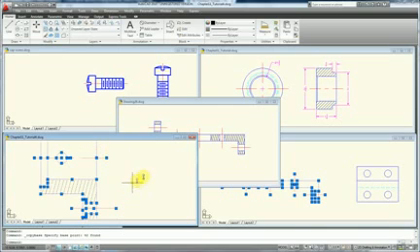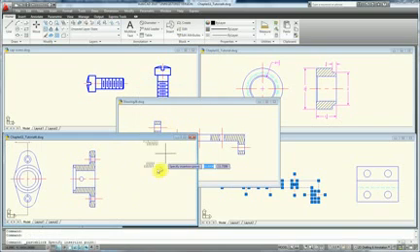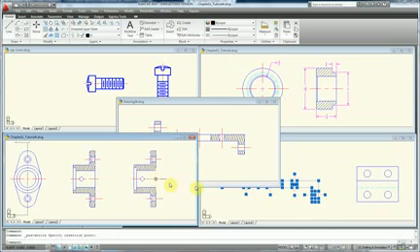So now I'm going to right click in this window and choose paste as a block. Now this geometry has been turned into a block as well as has a base point. So we're going to just paste it right there. We'll go to rotate in the modify toolbar. I'm going to choose this block, right click, choose the pivot point about that same base point, and then rotate it up.